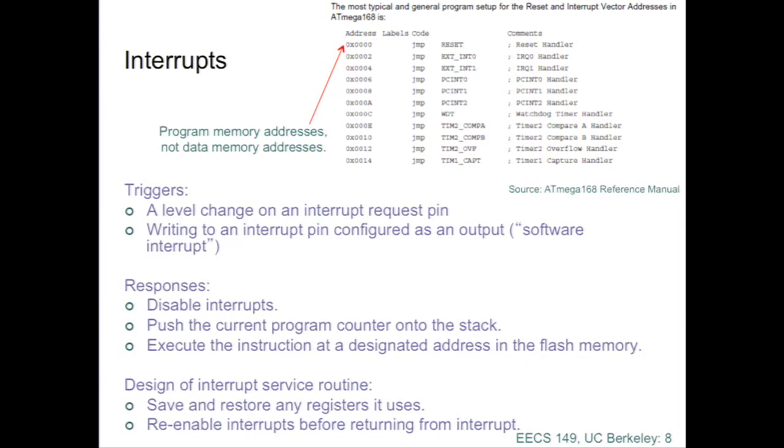And how does that saving work? Like, does it save that, okay, this particular register, so in this address, there's this value, this address, there is this value? Is this how it is saved? Or it just saves that, okay, these particular registers are reserved, and these registers cannot be used by the interrupt program? It can be done either way, but the most common thing is the compiler decides what registers to use in the body of the interrupt service routine, and then for the current value of all those registers, it pushes them onto the stack. Okay?